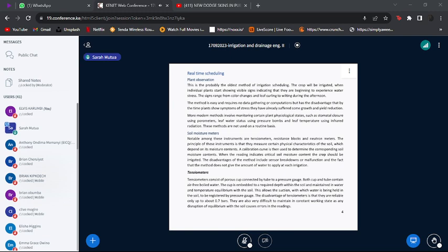Of course, we have some gadgets like tensiometers, electric resistance blocks, and neutron probes. The other method of measurement is the gravimetric method, whereby you get a sample of soil in the field and oven dry it for 24 hours. Remember, when you are doing that oven drying, your crop is using more water. So you have about a one day time delay. By the time you determine the moisture content is falling below critical moisture content, it will be a day later.